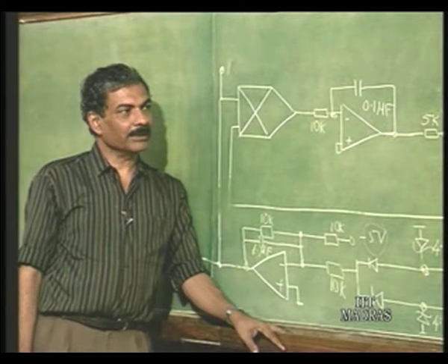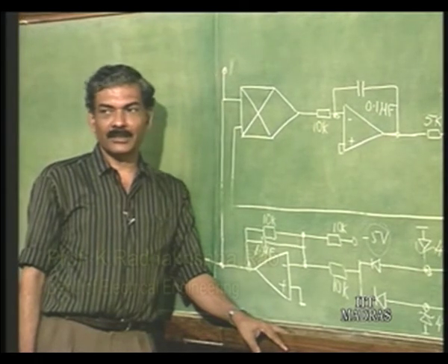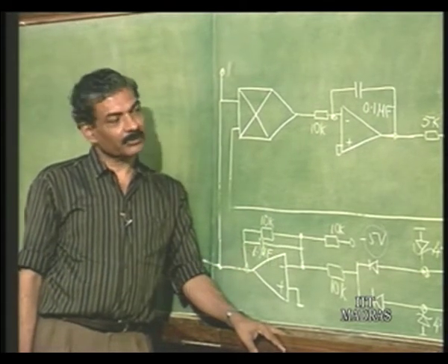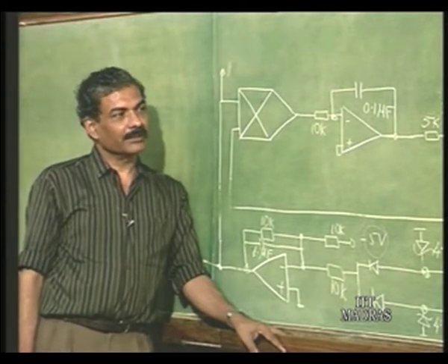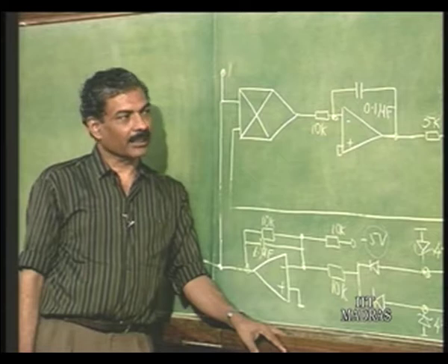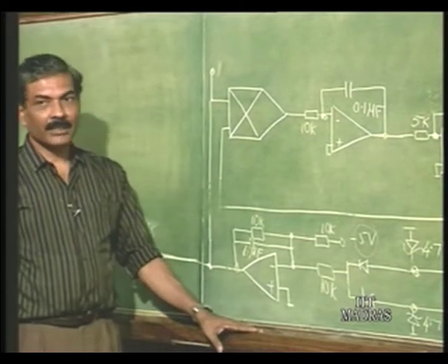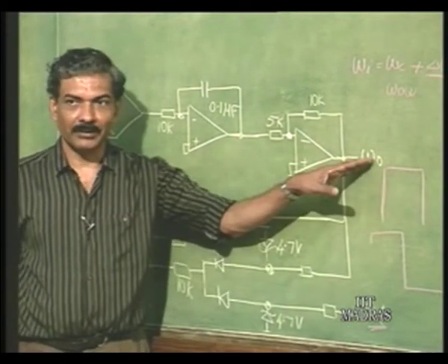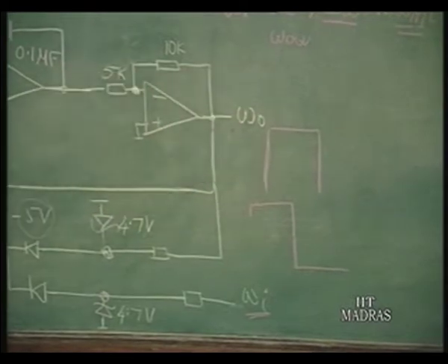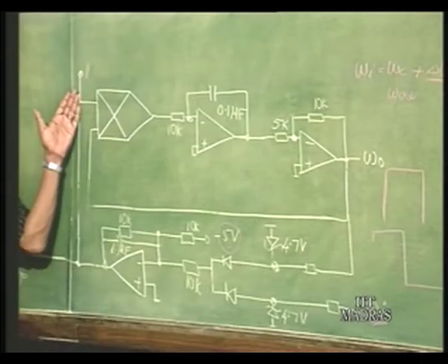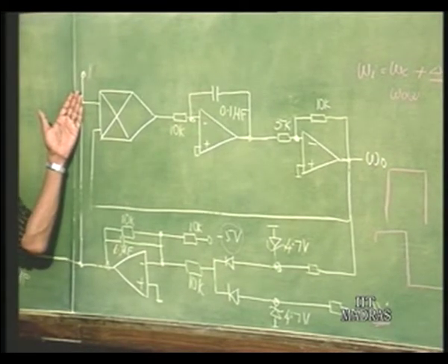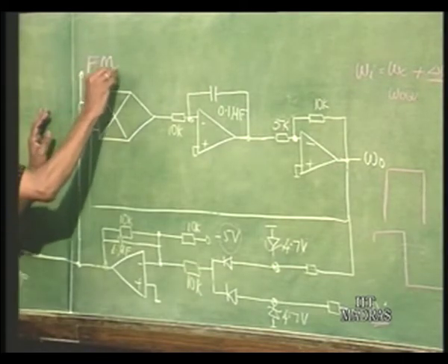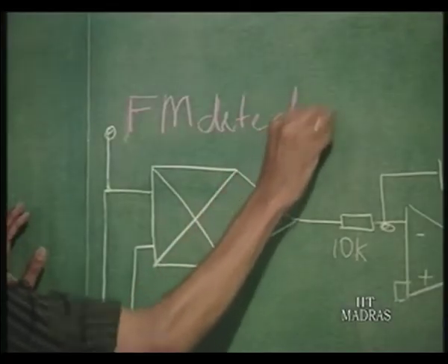In the earlier demonstration, you had seen signal conditioning effect of the phase lock loop, where FM at the input produces FM at the output, FSK at the input will produce FSK at the output, okay, of higher signal strength, better signal to noise ratio, etc. Now its application as FM detector, you will see. Obviously, if FM is inputted, FM is outputted at the output of the VCO. Now what is going to be the modulating frequency? That is straight away coming at the input of the VCO. So if FM is produced at the output, this is going to be FM detected output.